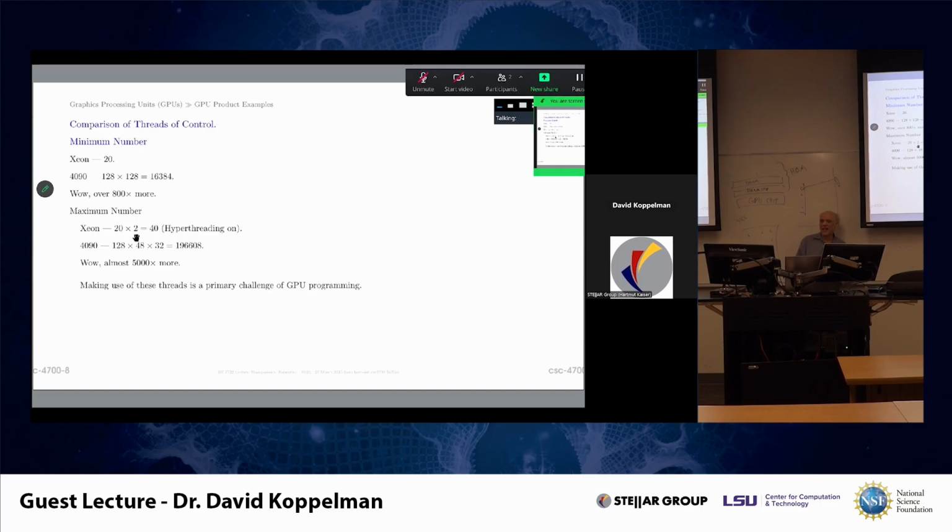In fact, it's not a context switch in the software sense, where you need to copy out the old registers and copy in the new registers. It's simply a decision on which context to fetch an instruction for. But once fetched, the instructions intermingle the 2 contexts. They operate together. They're in flight together. They share resources and so forth.